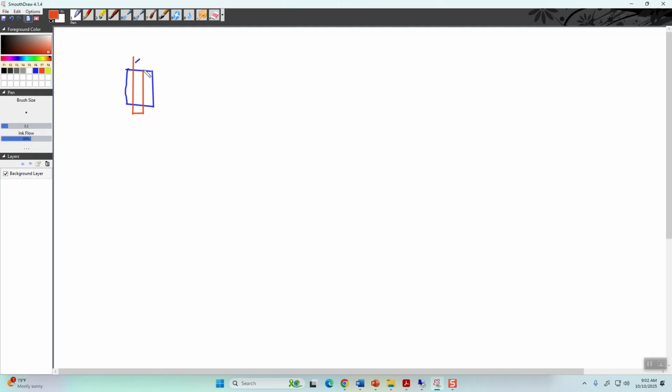And then this would be my gate. And what this implies is the blue would be an area that you grew a thin oxide, then you put a polysilicon, etched it, right? And then you did an N implant to turn these N-type, right? But even that is too much to draw.